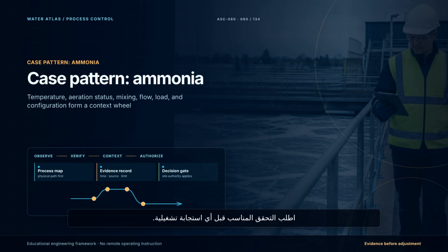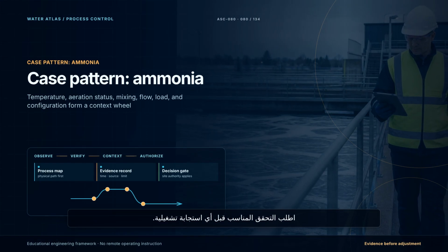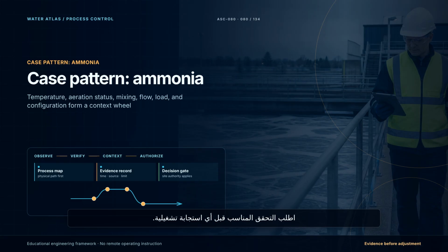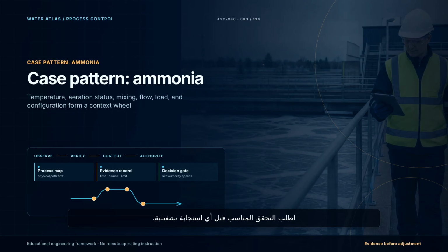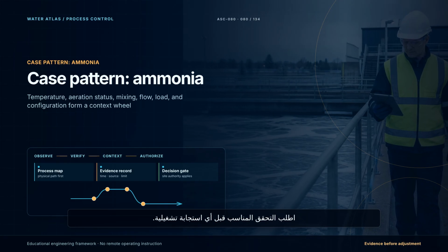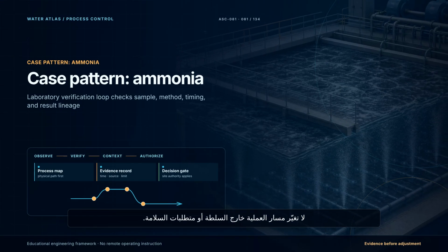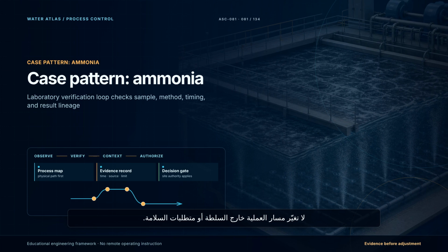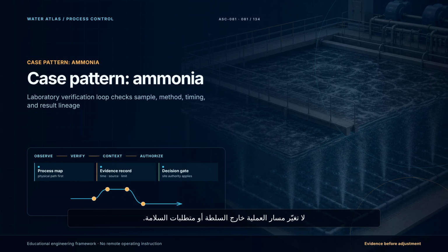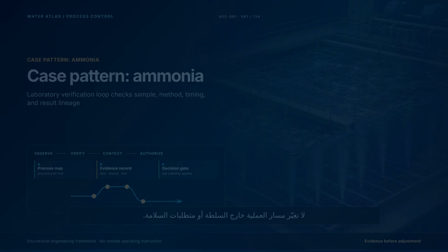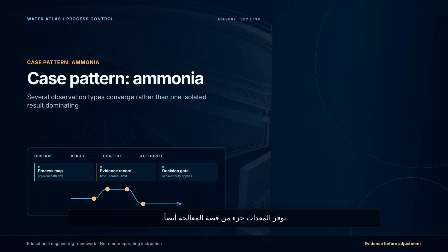Next, check the separation pathway. Review clarifier surface condition, solids carryover indicators, return and wasting system status, hydraulic changes, equipment alarms, and the reliability of blanket or solids measurements. In parallel, check whether a sudden influent event, upstream upset, or sampling issue could be contributing. Only then should the approved plant response process decide whether an intervention is needed.